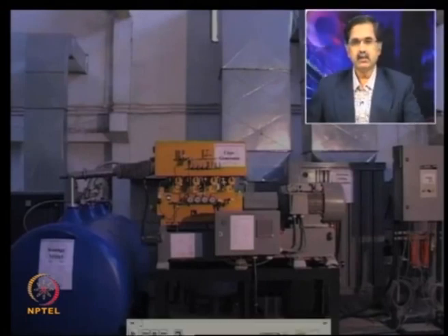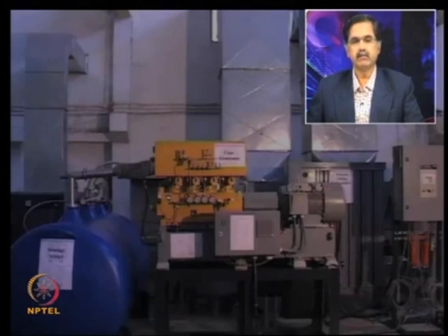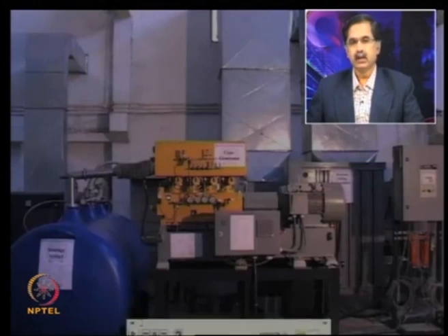And what you see here is a 4-cylinder cryogenerator which works on the Stirling cycle, and this is the common condenser to all the 4-cylinder machine. This is a Stirling cryogenerator and the liquid nitrogen is produced from this side and it is stored in this 2000 liter mother dewar, and from here it will be transferred to anybody who wants to take liquid nitrogen from our laboratory.